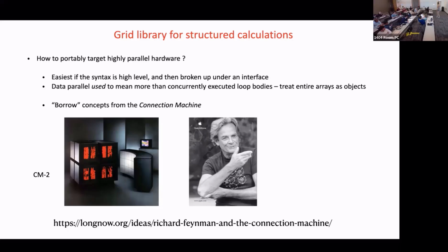The programming interface is much better if they do all of this and you figure out how, and then you can make different rules for how you break it down into the little atomistic things that are required. So specify a large level of granularity and break it down if you have to. If you have an interface that gets one word at a time and you must recognize from it that you have to instead program a DMA engine to send it all, that's much harder than just exposing an interface that makes it easy to program the DMA engines in the beginning, right? DMA meaning direct memory access.